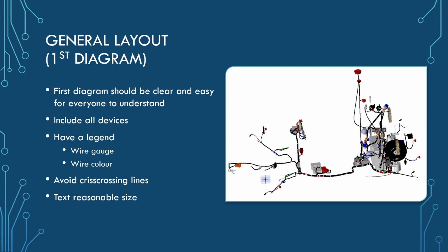In this stage, we're starting to think about the actual design of the harness, and more so, like I said earlier, mixed up with placing where everything is going, as well as figuring out where the connections are going to and from. So like from, let's say, the right wheel all the way up to the dash, or off to the side of the frame through the firewall and stuff like that, basically.